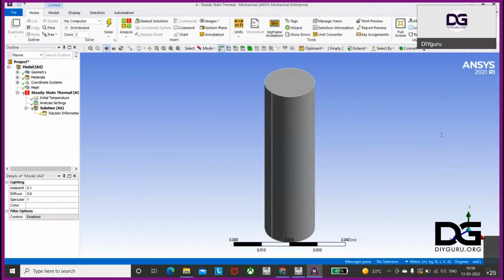And on that basis, with the whole design of the motor, you go to a motor controller manufacturer. Then on the basis of looking at the motor datasheet, performance curves and everything, he suggests the motor controller that will deliver that much peak power or peak current at that voltage rating. For example, if you're taking a motor of 72 volt, we provide you a motor controller of 72 volt. And then based on the architecture of your motor controller, you design a battery pack, like whether you want to go with 1C or 2C.